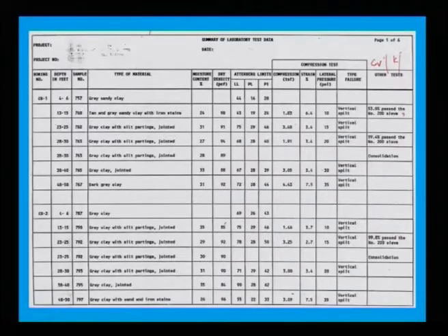Page number 3, 4th onwards, first you give a summary of detailed laboratory test data, including all the CV, K, all the laboratory tests whatever we explained. If you have done cyclic tests, you can also provide the shear modulus and how it is varying. Also soil stiffness values, E, mu, G, if you have done these tests and want to incorporate them, you can provide them depth-wise. This is your detailed summary of laboratory test data, your third part.